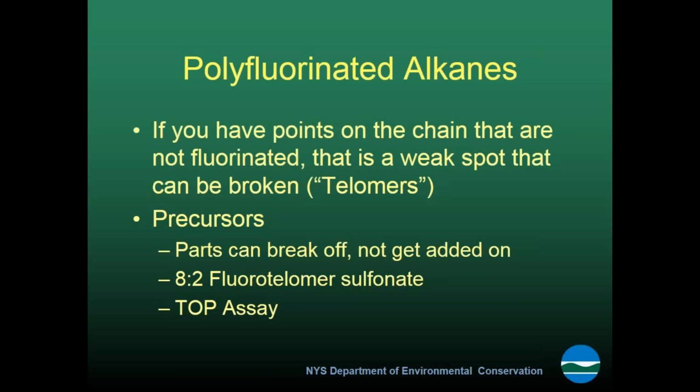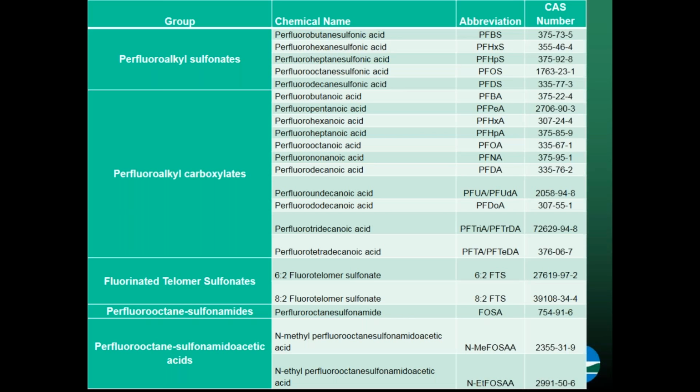We've had such tests where in the first test before oxidation, we only had a couple parts per trillion of PFOA. After the oxidation, we had over 20 parts per trillion of PFOA and PFOS. There are states where that would be above the standard. So we definitely have seen situations where you can have an order of magnitude increase from the precursors.